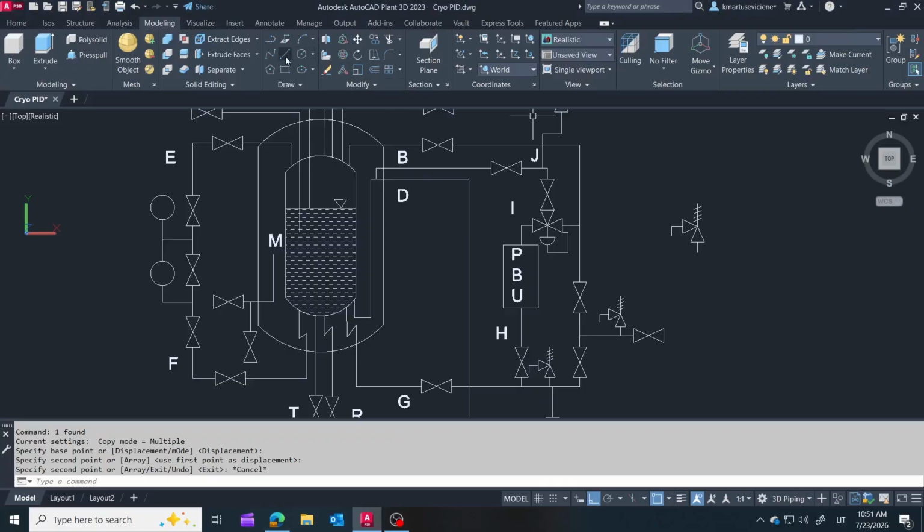Next, I'm adding the drain valve for the fill connection. After the filling operation is complete, a small amount of liquid nitrogen can remain trapped inside the fill line. This valve allows the line to be safely depressurized and drained before disconnecting the transfer hose.